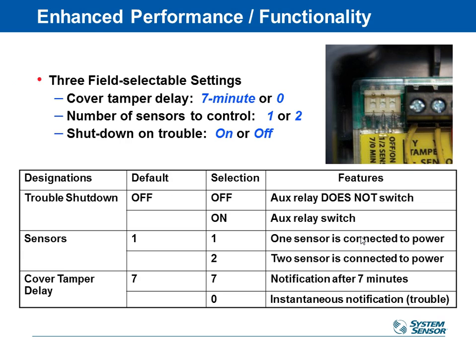You can set that up to happen immediately, or you can set it up to happen after 7 minutes. 7 minutes is the most common way that I have set them up previously. Then I've got time to put the cover back on. The other thing you can adjust is whether it has 1 sensor connected to that power board or 2 sensors connected to that same power board. So that was that supply return system that we showed you previously.